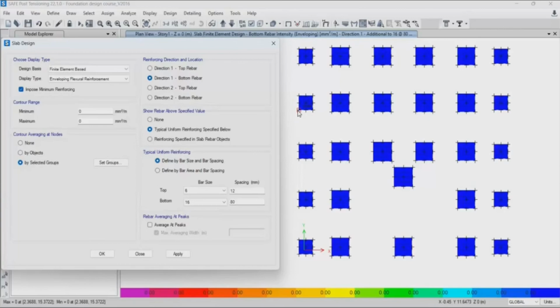Because it is not going to cause problems with excavation. But if the total area of the individual footings is more than 50%, let's say it is 60 or 70% and above, then you need to stop providing isolated footing, because going with isolated footing is going to be a waste of time, a waste of resources, and it's going to be very difficult to construct on site. So in that case, you just provide one large area for your footing, and this is what we call the raft foundation. Okay, so I hope you are understanding this.